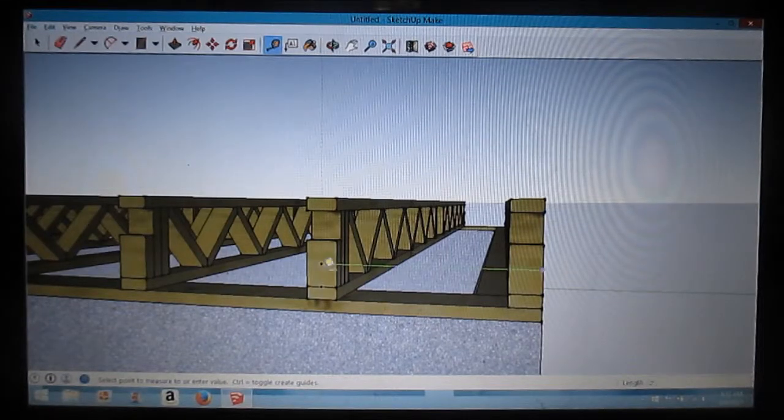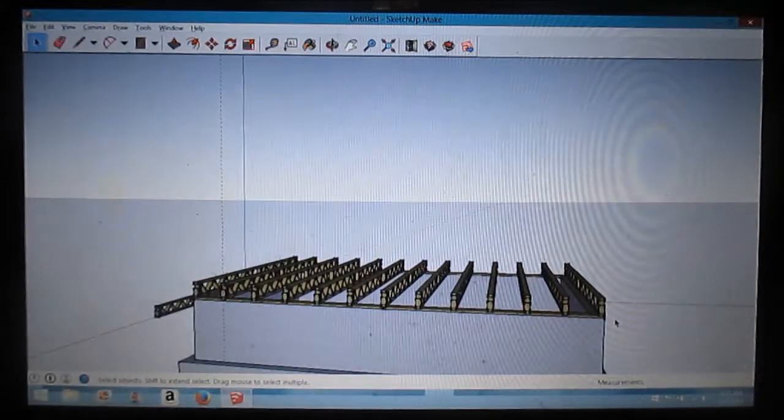There we go. Yeah, 2 foot. See how that's 2 foot to the center of that from the edge. Now from the center there, every center is 2. That'll be 4 foot. 4 foot to the center. Okay. I just quickly built all those trusses.